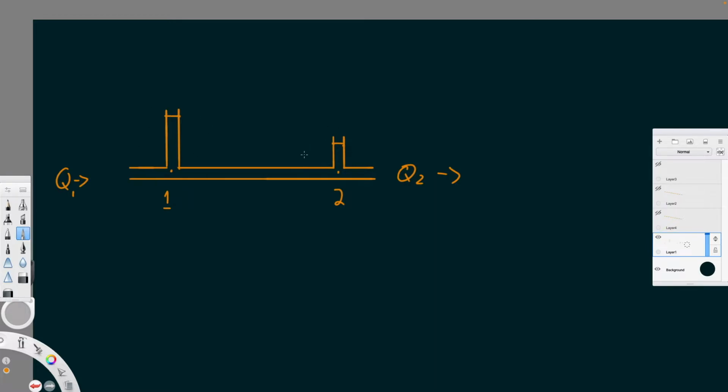And then what look like pipes sticking up are known as piezometers. Essentially, the greater the pressure, the higher the height of the fluid, so it's a way of measuring fluid pressure in terms of height of fluid. You're going to have some component of elevation, right? In this case, with a horizontal pipe, the elevation really is kind of arbitrary. So let's just say we have Z1 and Z2 at the center line of the pipe, essentially 0 at point 1 and point 2.